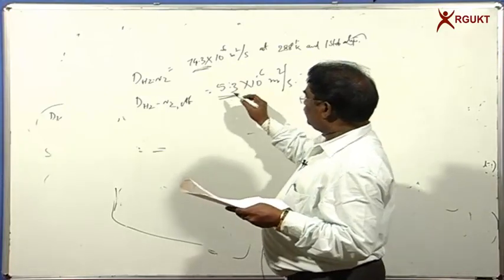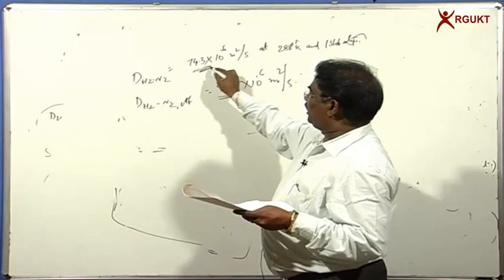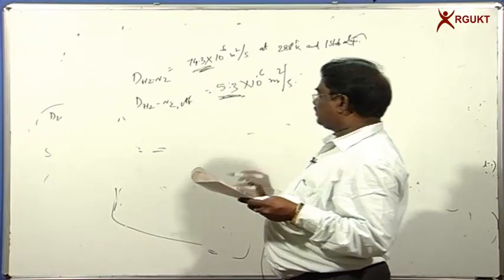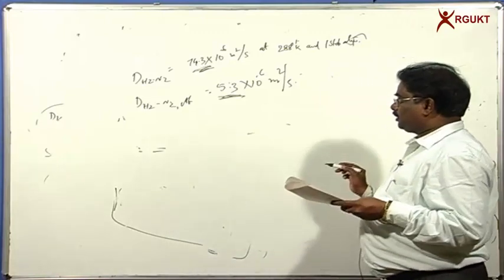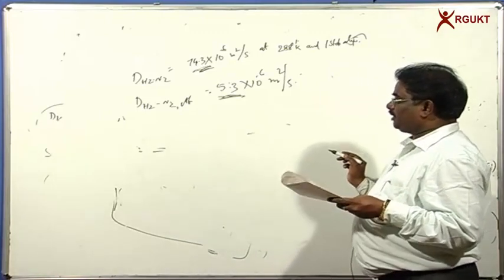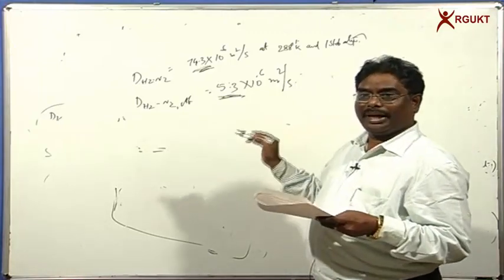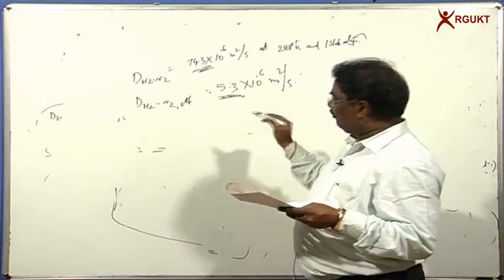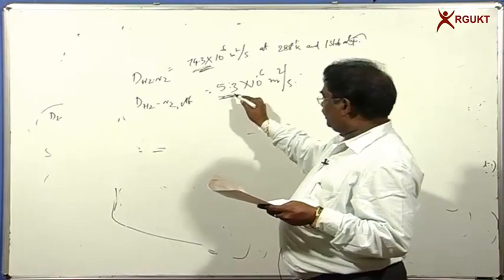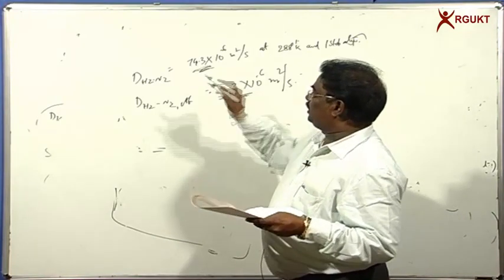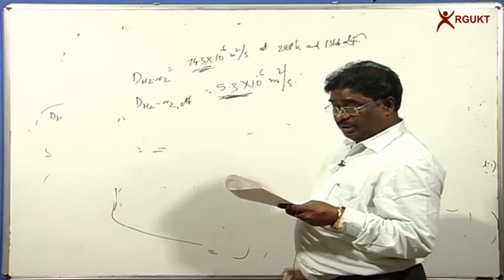This is because we are using a gross surface area to calculate the actual diffusion coefficient, but in porous systems we cannot use the gross surface area, and we have to use the actual surface area, and it is not possible to calculate the actual surface area. However, we are estimating diffusion coefficients. That is the reason the effective diffusion coefficients may be 14 times lower for this system.